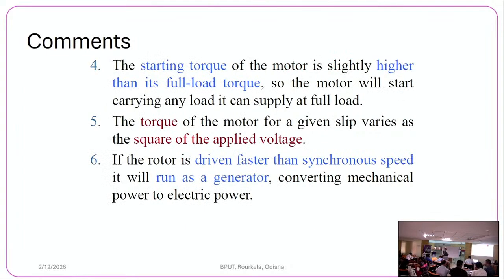The starting torque of the motor is slightly higher than its full load torque. The motor will start carrying any load it can supply at full load. The torque of the motor for a given slip varies as the square of the applied voltage. If the rotor is driven faster than synchronous speed, it will run as a generator, converting mechanical power to electrical power.